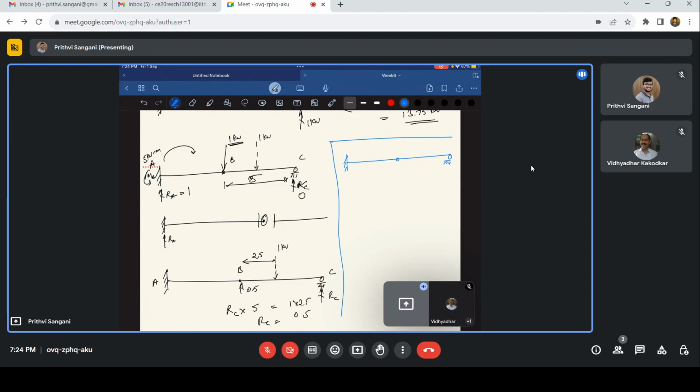So we are asked to find the bending moment at A. How much should be the bending moment at A? So it is very simple. If you are asked to find the bending moment at A, we'll assume a hinge there and we'll rotate it in such a way that the theta is 1. So what are we trying to do? You are asked to find the bending moment at this position, so you'll just rotate in such a way that theta is 1. As this is a hinge, this can deflect downwards. It can also rotate, right?